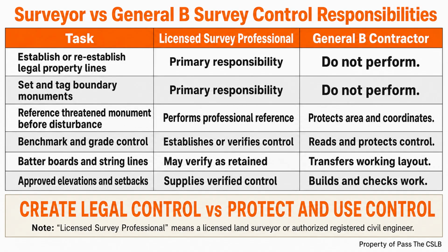Survey control is valuable because construction depends on repeatable reference points. A benchmark gives the project a stable elevation reference. Grade stakes communicate where planned grades or elevations must land. A property corner or boundary monument carries legal meaning. Finished floor elevation tells the crew where the completed floor is intended to sit relative to the project control. These items are connected, but they are not interchangeable.